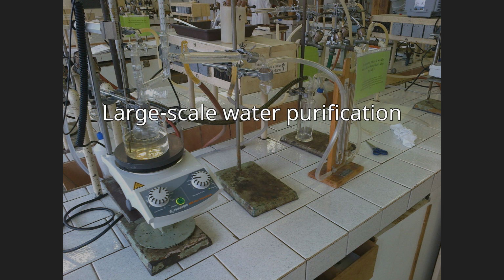The heat removed from the water vapor is removed by a heat sink and passed into the incoming ocean water to preheat it. This reduces the energy requirement and allows for much higher efficiency due to the reduced requirement for heat and fuel usage. Some forms of distillation do not use condensers, but instead compress the vapor mechanically with a pump. This acts as a heat pump, concentrating the heat from the vapor and allowing for the heat to be returned and reused by the incoming untreated water source. There are several forms of vacuum distillation of water, with the most common being multiple effect distillation.